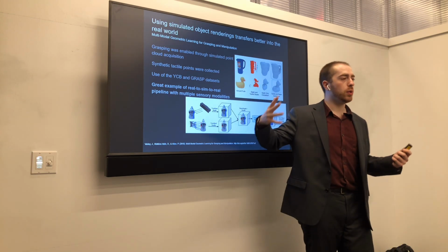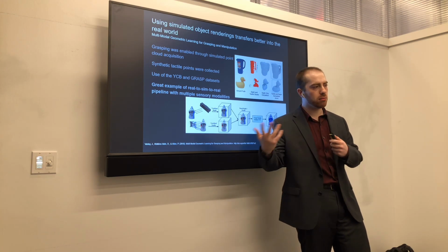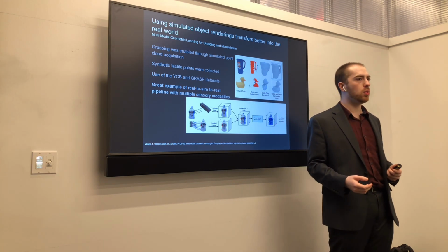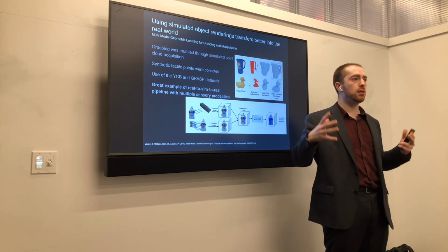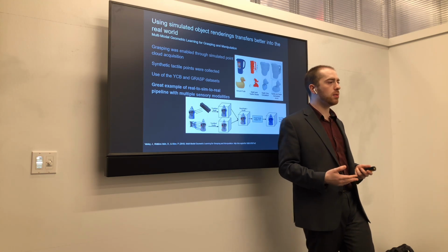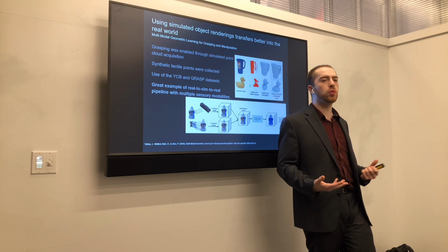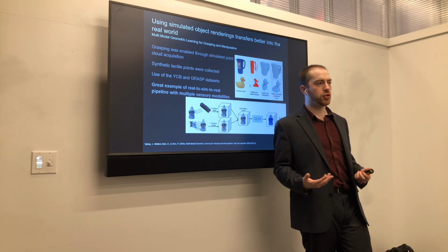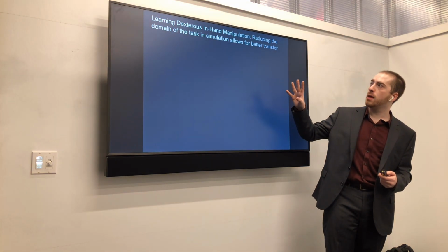I didn't mention, we were using GraspIt to perform the grasp planning in simulation and then executed those grasps in the real world. And we trained the model using synthetic RGBD point clouds and also synthetic tactile touches on the occluded side of the object. So there was no real data collected for training this particular pipeline.